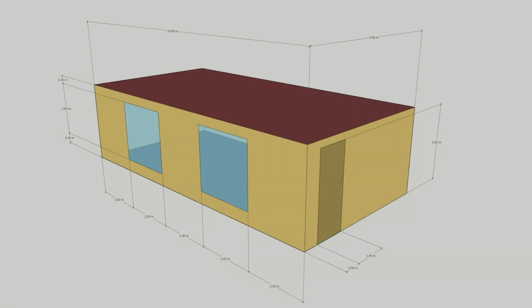We're going to kick things off by building a simple model with just one space and a single thermal zone. Take a look at the geometry shown here. For this exercise, we'll focus on defining the envelope geometry and constructions for this basic building. This setup lets us simulate how the envelope responds to weather conditions without any conditioning. Later on, we'll add internal heat gains tied to how the space is used, and we'll revisit this model again to include an HVAC system for space conditioning.